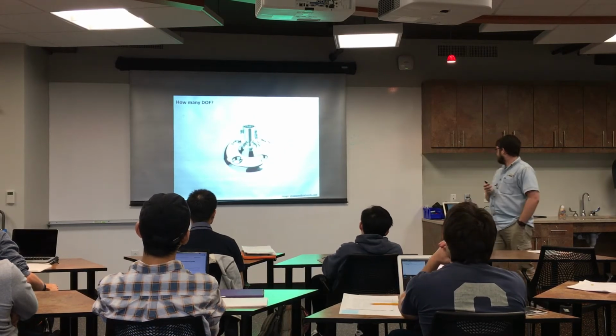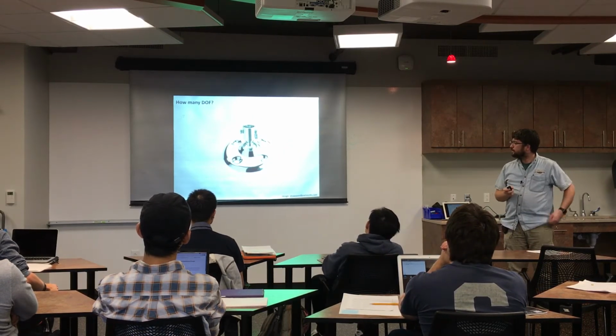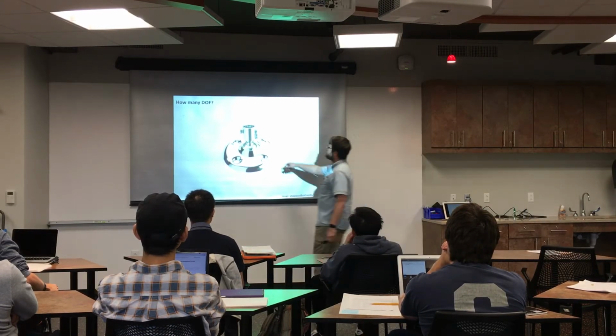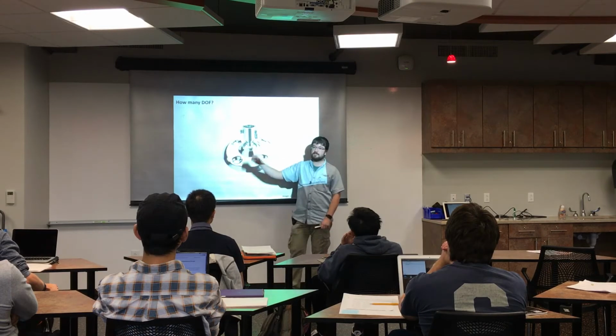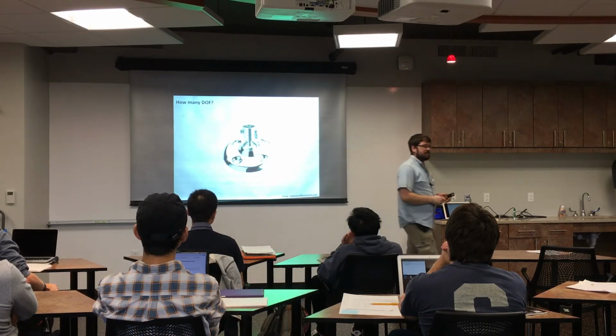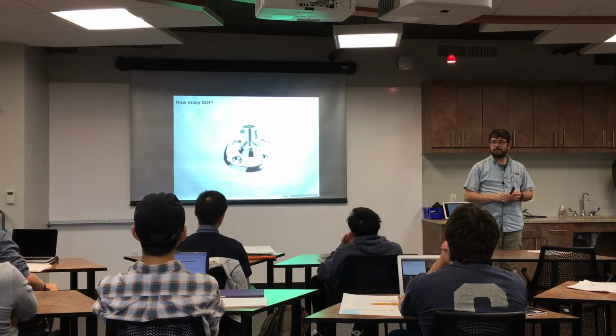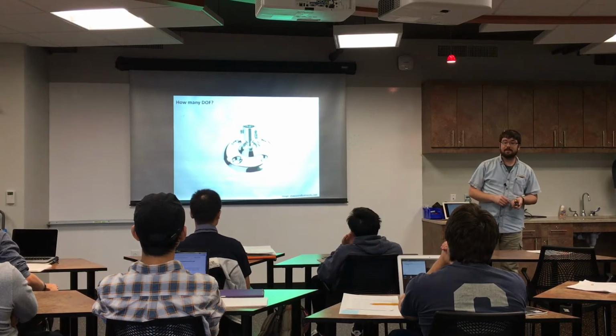All right, I think there's just one more here. This is one of those little, you could think of like a flag holder or something. You could mount it on the side of your house and put the flag in there and position it. So how many degrees of freedom does this have? And it's kind of tricky. 5, 4, right direction. So 3 degrees of freedom.